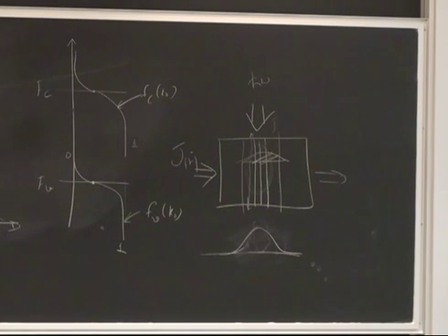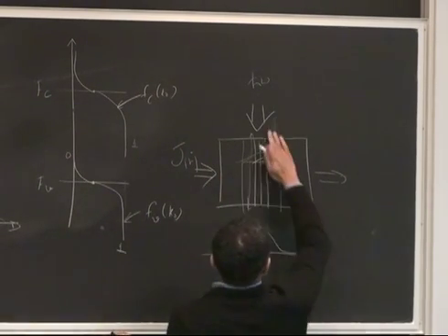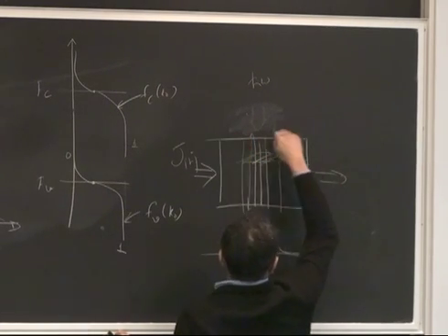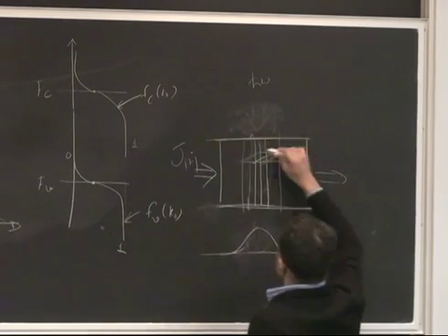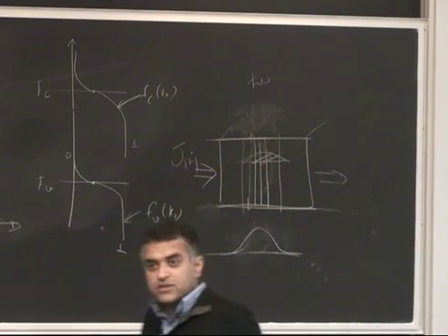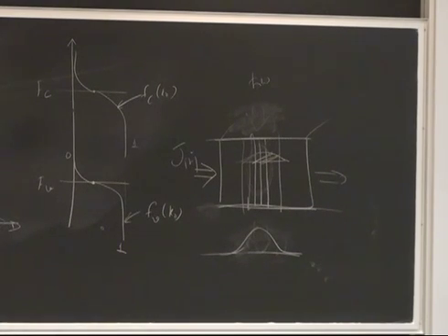For example, in this particular picture, you can change it depending upon the refractive indices and such. But the intensity of light kind of starts looking like that. And what you can do now is you have the option of making a laser in two ways. One of them is you take this LED structure, and then you cleave the crystal along two directions here and expose a very almost atomically smooth facet. Cleave it, make it almost atomically smooth, and that's a mirror.